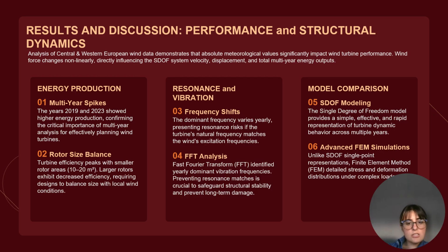Regarding the frequency shifts, the dominant frequency varies yearly, which presents resonance risks if the turbine's natural frequency matches the wind's expected frequencies. Here we also did some fast Fourier transform analysis, which identified the yearly dominant vibration frequencies. Preventing such matches is crucial to safeguard structural stability and to prevent long-term damage.